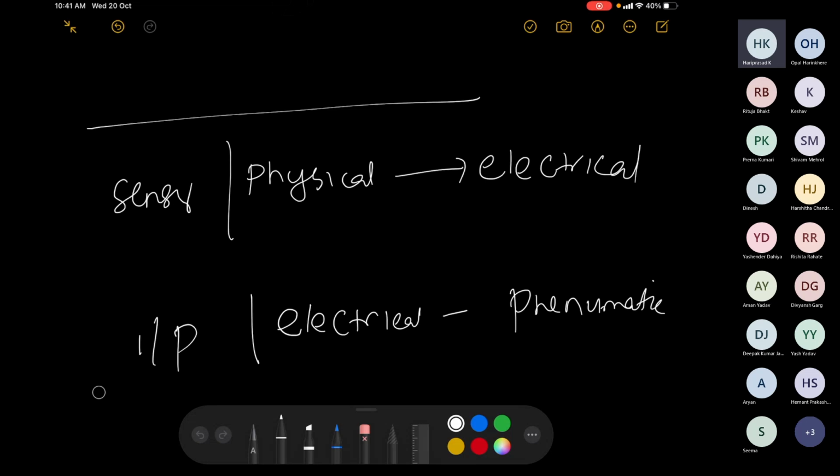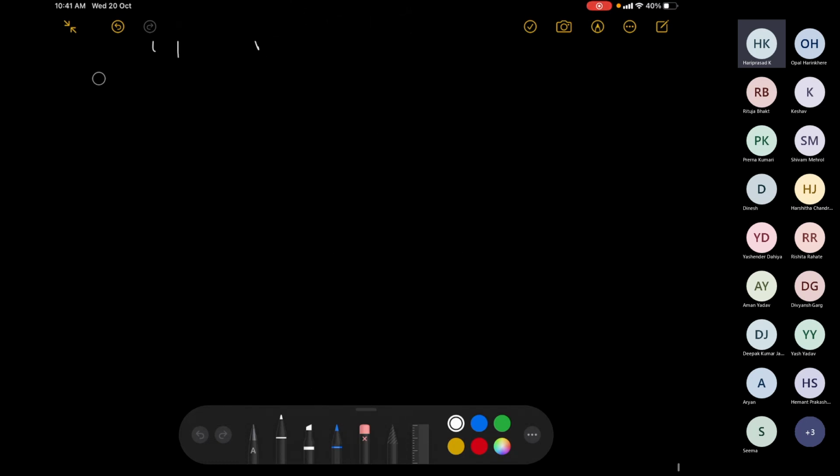Now coming to the sensor. The sensor will have its own dynamics, for instance Km by tau m s plus 1, or it can be just Km for simplicity. This happens in the transducer or sensor. Let's look at that block again. There is this comparator and the sensor output coming in.